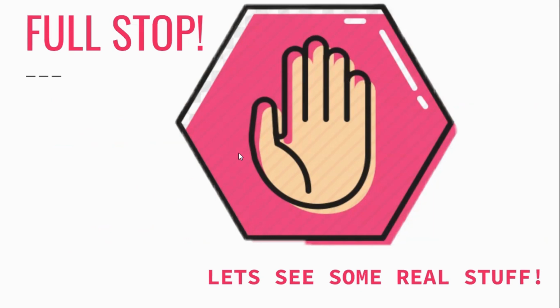We did talk about when they freeze, but also AC drains, especially in Florida and in humid climates, Louisiana, Tennessee, Alabama, you'll find drains that have what we call drain snot in them. And it very equivocally looks like a giant snot that comes out of your drain, but it does plug the entire drain line. So you won't have very much flow past that. So if you're on a maintenance and you're not blowing your drains out with nitrogen or with hot shot CO2, if you're not doing that, you need to be doing that, especially in the summertime. So full stop.